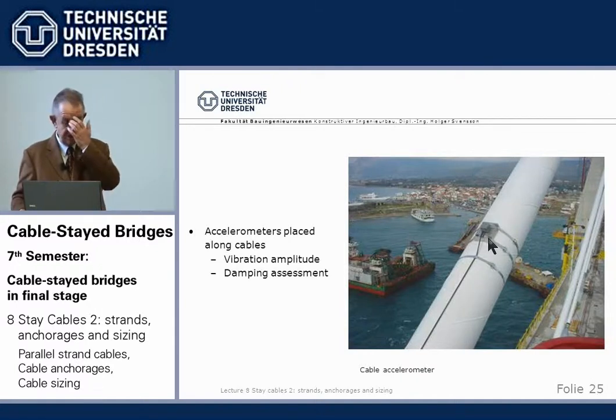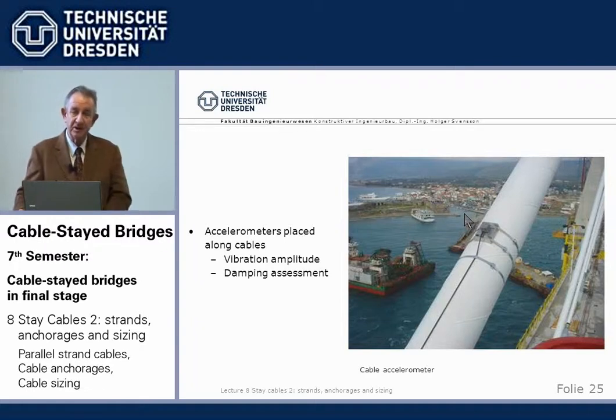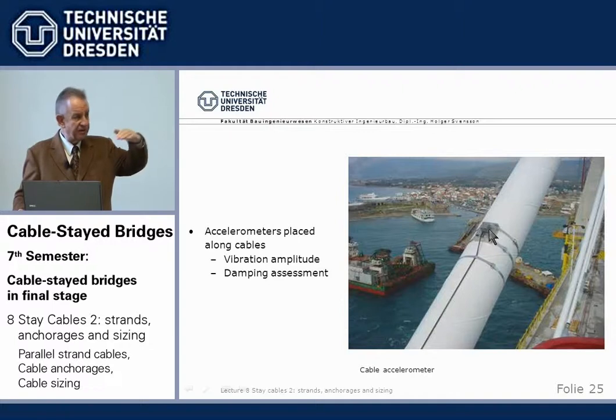One thing which we can do is we can place an accelerometer on a stay cable, which measures the accelerations, not the velocity, but the acceleration which a cable exerts when it vibrates. And by these accelerations, they are directly, of course, connected with the amplitude. We can find out with how many amplitudes a cable vibrates due to the various reasons. We'll have a special lecture on that. And of course, from the decline of the oscillations, we can then assess the actual damping due to whatever reasons. So we can measure that.